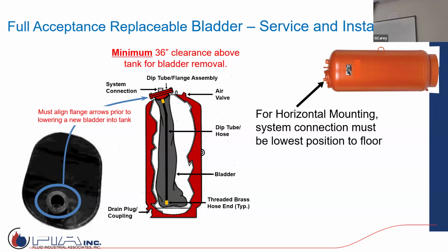Makes sense. But then the insurance inspector who's inspecting for the insurance company does his inspection and he's looking and saying, hey, that's a 50-pound relief valve on your boiler plant. These are non-ASME tanks. They're going to be ASME to meet the code. So stuff like that, 400,000 BTUs, fill pressure. Over 30, 30 and under.